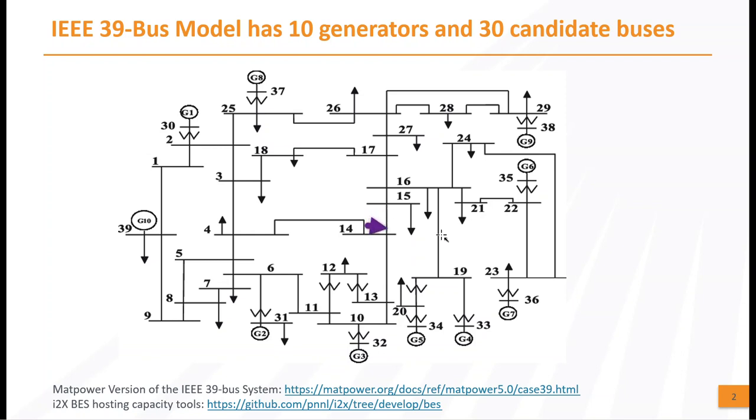Okay, so we'll do that fault with both of these other 2 lines in service and with one of them out of service. And so when we set up an N-1 contingency condition and we take the second line out of service, there's only one line there to export power from bus 14. So it is another line coming out of service from an N-1 condition. So it's fairly severe. But we want to set up some scenario where maybe a plant that looks like it would fit based on a hosting capacity analysis result wouldn't really when you did a detailed design study or interconnection study.